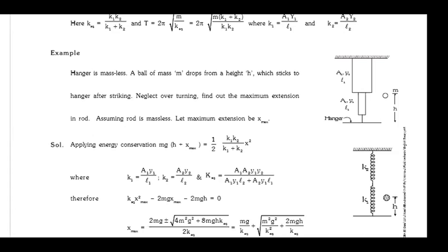Yes or no? So that will change my delta L, right? So instead of delta L, I can write delta L is equal to what? Tell me. L into alpha delta T. Yes or no? Delta L is L into alpha delta T. So this is one more concept that can be asked. This will lead to thermal strain, which again will lead to thermal stress. Okay, got it?